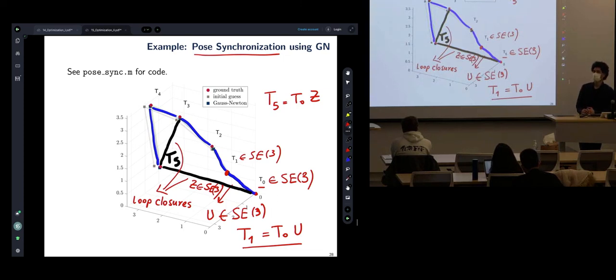In reality, the front end of the SLAM, as we will talk about it, is responsible for constructing this graph. And it's important how you do it, because if these edges are wrong, if they're outliers, then your solver might break down, which is the importance of having an M estimator to some extent ignore wrong edges.